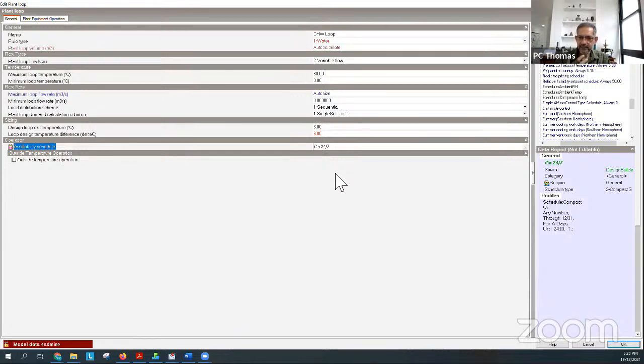Now, when is this chilled water loop available, so that if there's a demand for cooling, it can work? If you are in an office building, you will switch off the system at the end of the day and go home, start it up again in the morning. So this on 24/7 is not useful.